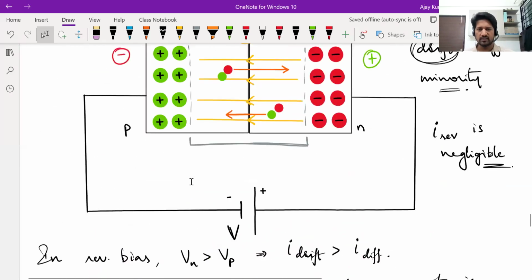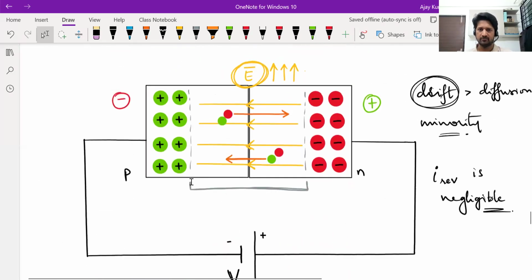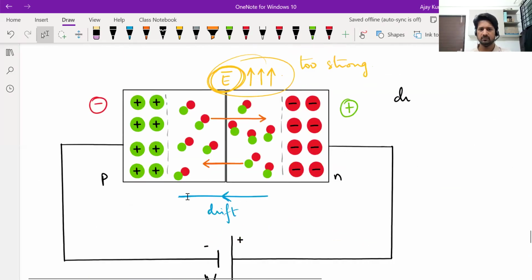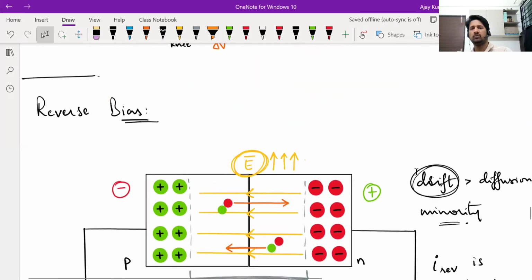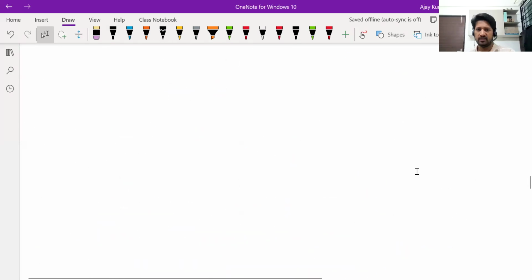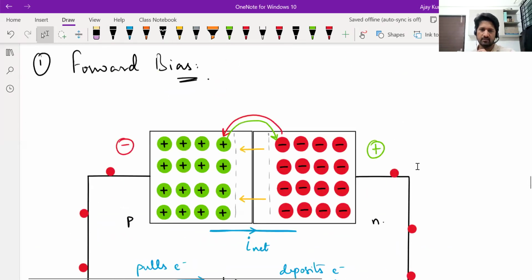Okay, so understanding this process is important. Why there is very small current in reverse bias and why it suddenly increases when the voltage crosses a certain limit. Fine. So this property of a PN junction to allow current in one direction, okay, that is the forward direction. It allows current from P to N easily if you bias it in the correct manner. And to stop current in the opposite direction, when you do reverse bias, the current is negligible. Okay, provided there is no breakdown that happens.